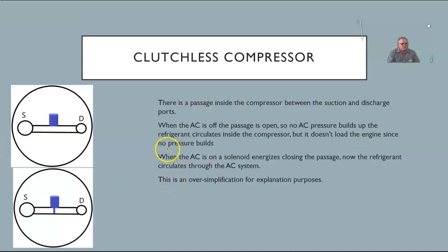And connected in between there is going to be a passage. If you don't want the AC to work, that passage is open and refrigerant's just going to flow out the discharge right back into the suction. It's not going to put any load on the AC compressor.